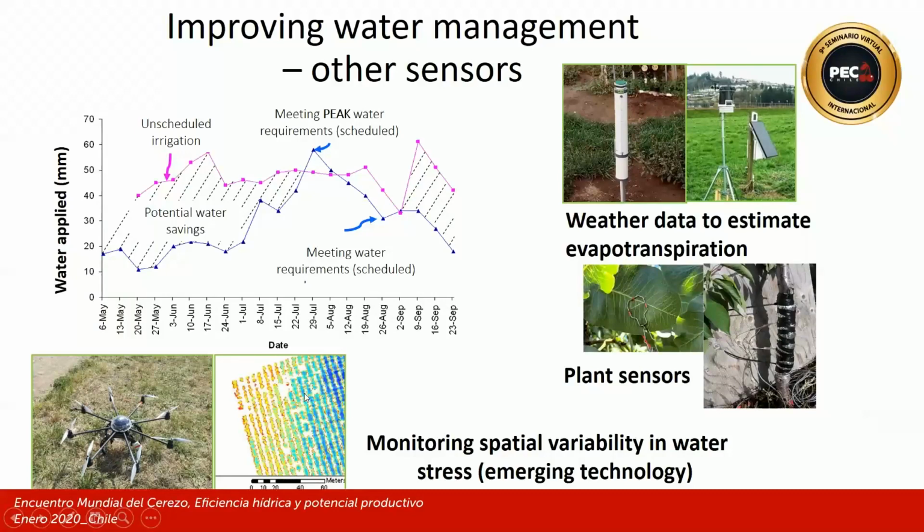Remote sensing technology is also being deployed to assess spatial variability in plant stress and in soil water supply. One of the greatest challenges in precision water management is spatial variability. How to measure it? Do we need many sensors? And how to irrigate appropriately in response? At the moment, drop tube center pivot systems linked to soil moisture monitoring are the most commonly used systems to overcome soil moisture variability. But these are not suitable for tree fruit production.